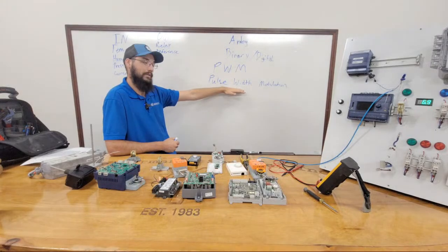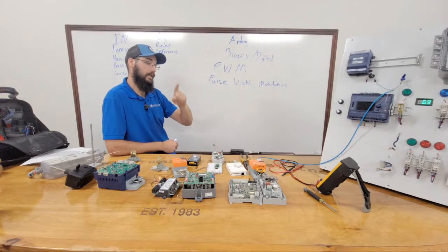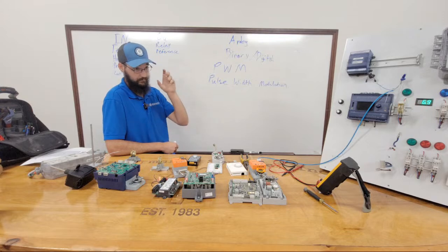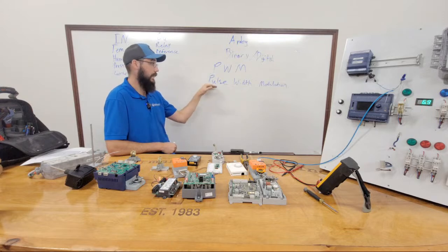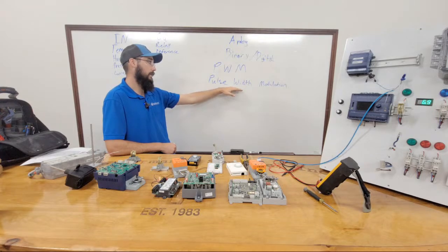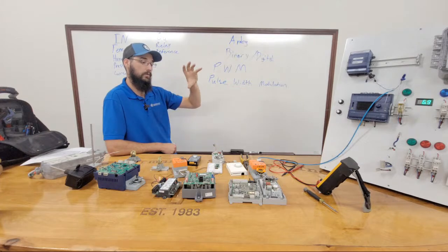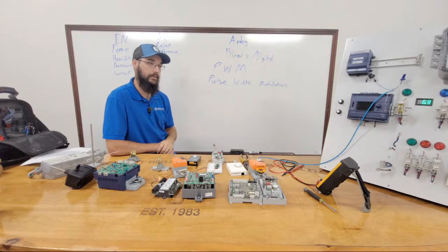They could also be pulse width. And SCRs themselves, so a solid state, or the silicon controlled rectifier, what makes an SCR what it is technically, it is a PWM signal to the voltage going to the heaters.